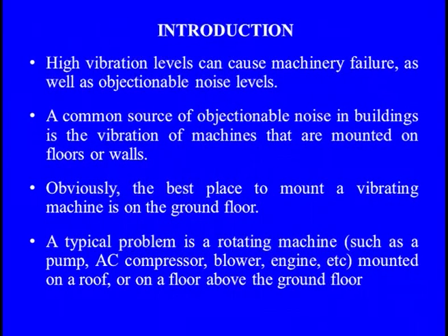We know the basic theory of vibration, that high vibration levels can cause machine failure, because the dynamic forces are of a fatigue nature. When cyclic loadings are applied to any structure, and the system is excited in its higher harmonic modes, it can straightaway damage the machine itself.